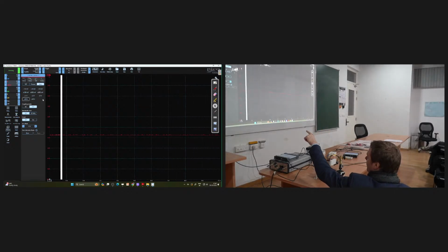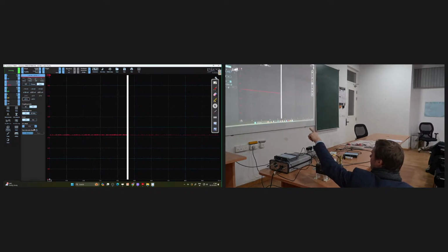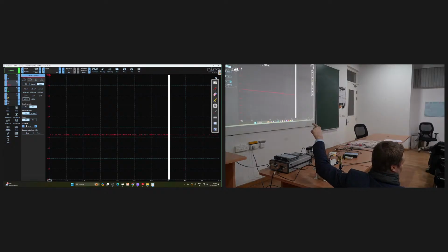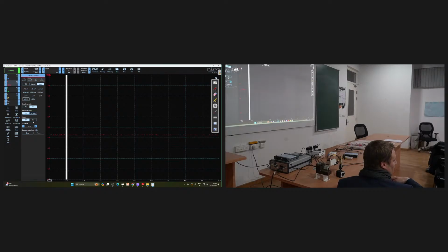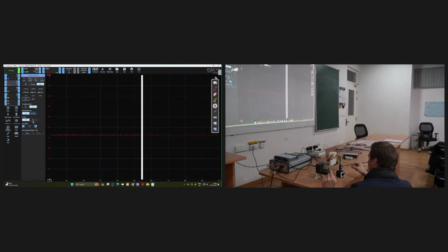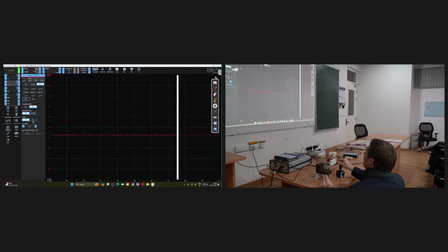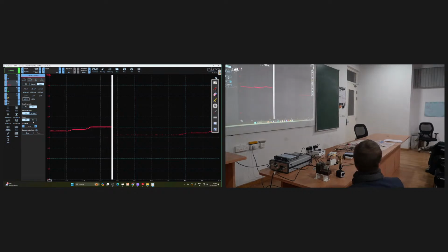Maybe you can hover with the mouse over the DC offset. So lower, lower, lower. Yeah, that. So that's the DC offset of negative 5 volts, just to put it down. So now I can go up and down, 5 volts up, 5 volts down, because I have the negative offset. And the first thing I will try to do is to get it to 0. Let's see whether we can do that. I have a small wheel here, and with that small wheel, now it's at 0.